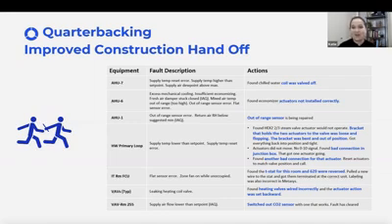Coils that were valved off, actuators that were not installed properly, sensors that were out of range. These were all things that could be handled by warranty. So not on our dime, on the contractor's dime, all within warranty, and you find them fast, which is why that's so important, because if you let this drag on until 2 or 3 years later, when you start to get familiar with the building and how it's supposed to operate, and you get that institutional knowledge, it's too late. And then you're fixing all of this stuff on your dime.